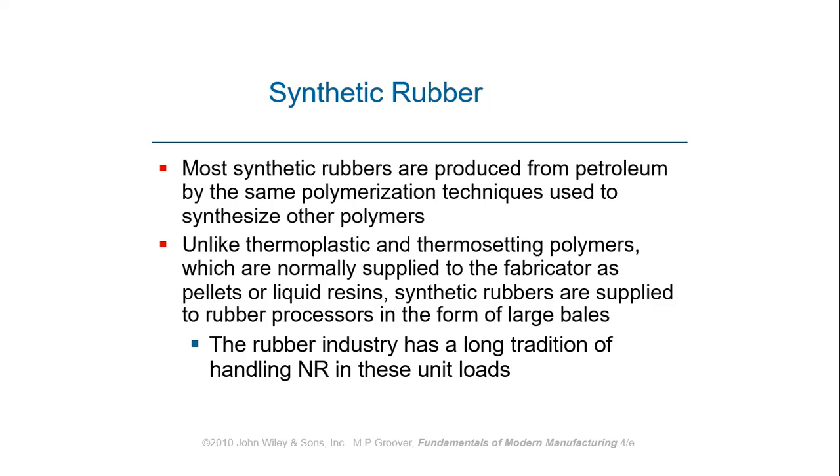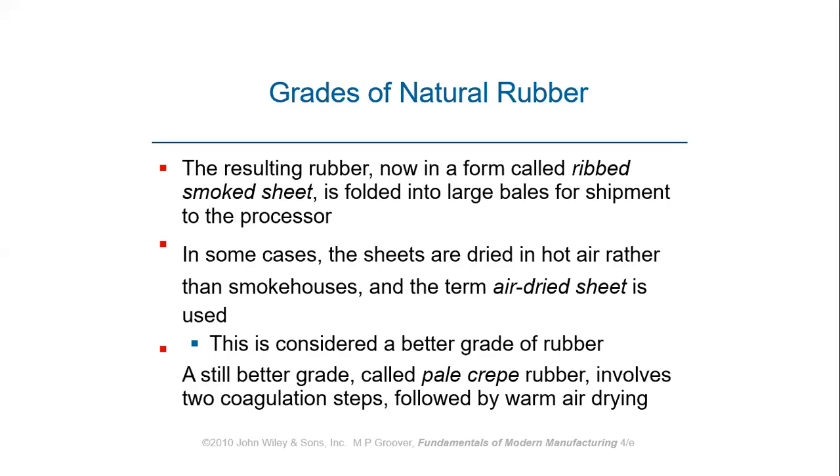So so far we are not going deep into the synthetic rubber manufacturing. It involves just the chemistry to form the long chain rubber polymers from the petroleum. So we're not going into that, but in the case of natural rubber, the whole process, if I want to summarize, is that first you take the liquid extract from the rubber tree, and then that liquid extract is mixed with the stearic acid for like 12 hours.